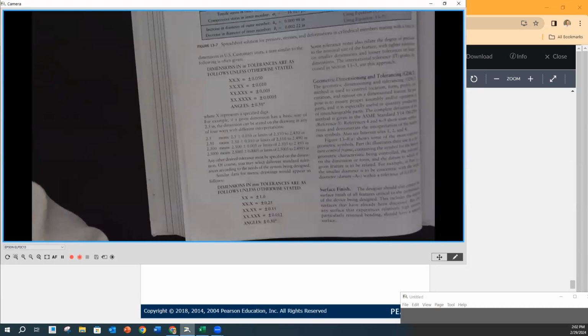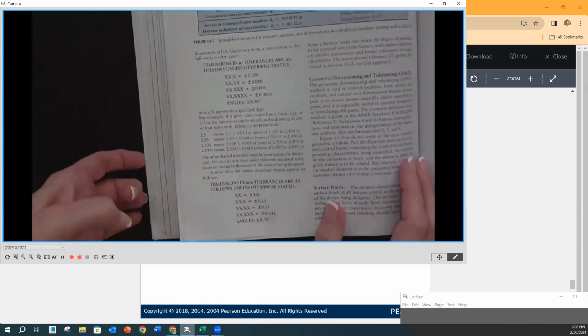And again, I can't emphasize enough, you never change a title block tolerance just because, oh, I didn't use those on this drawing. Okay, ever. And it might seem like, yeah, that doesn't make sense, but it can escape some people sometimes.